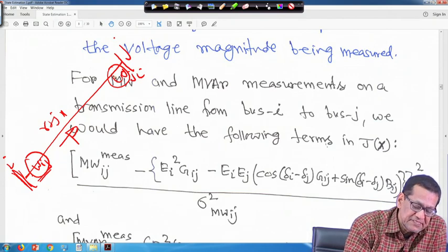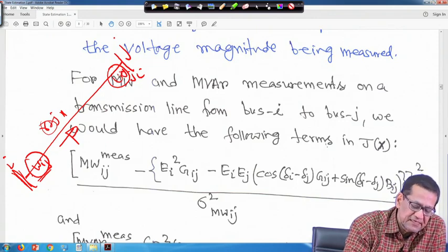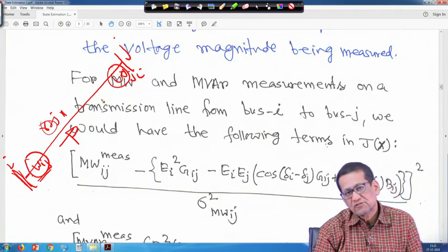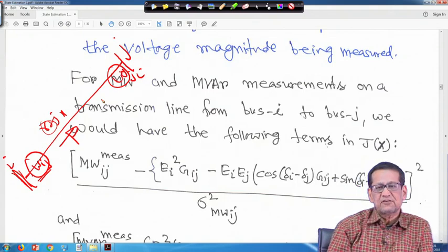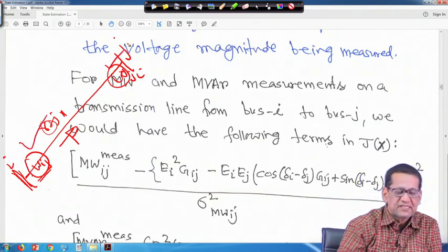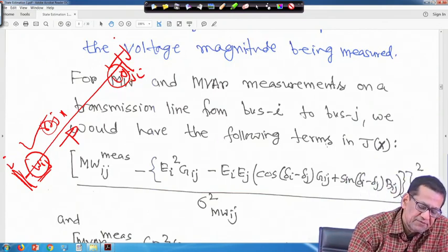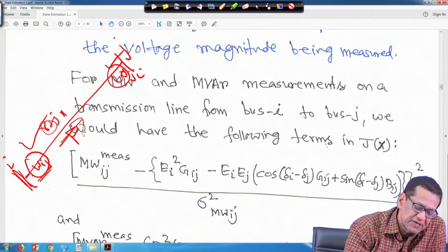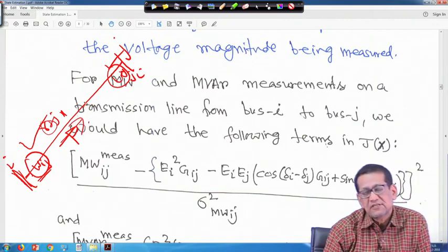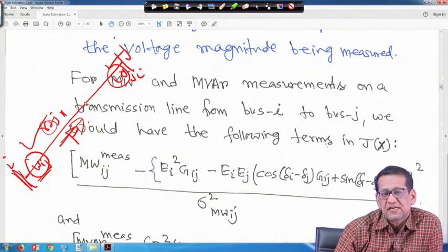So, if you try to measure here, it will not be the same, because the line has R, so it has loss. Whatever it measures here, that loss will be excluded. That means if you assume a lossless line, that is R is not there, then this reading and this reading you can take as the same, but the line has loss. So whatever the reading of this wattmeter, the direction is this way, right. It will be this one minus the power loss in the line, that is I square R, which will be subtracted; that will be the meter reading, right.